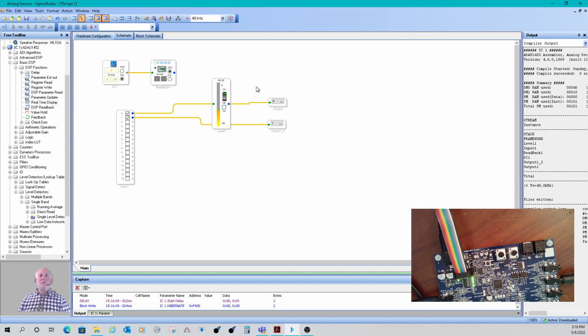Okay, I got some noise floor, but that's not necessarily bad. And voila, I can see music. And this is just because I got 2 different computers and there's a ground loop. I should try to solve that. But anyways, see if you got audio coming in. And if you have audio coming in and you're still not hearing it, then okay, let's focus on the output.